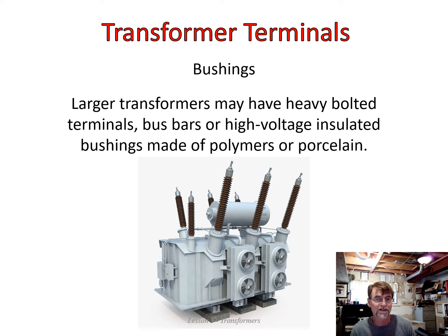They also provide separation from the wire and the transformer itself. Remember, the transformer, you can see it there, is made of steel. It's all grounded. So you certainly don't want the wire to arc to the transformer housing itself. The bushings offer that protection also. They're very large insulators. They keep everything well separated so that there's no potential for arcing.